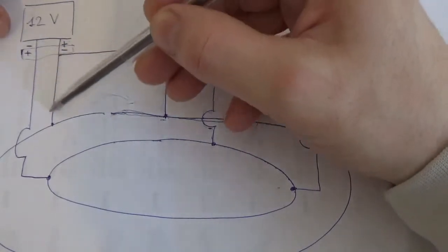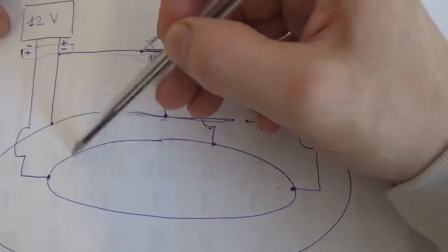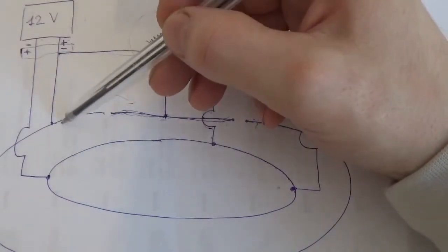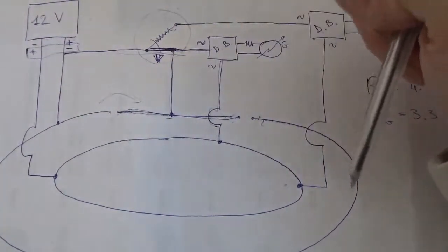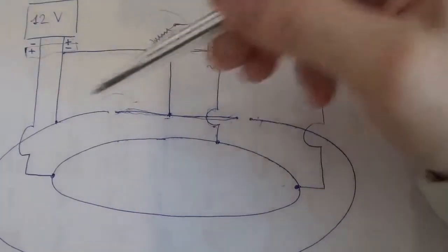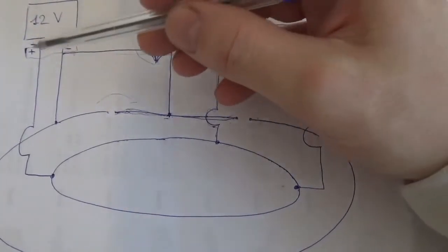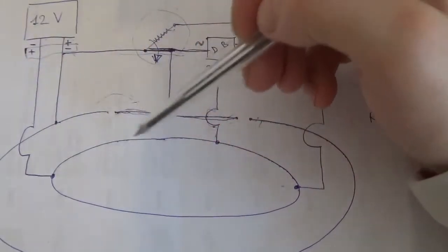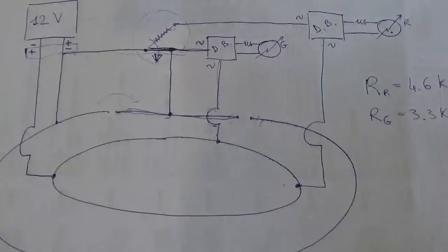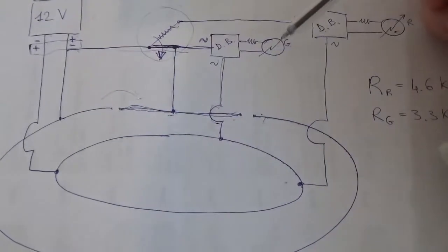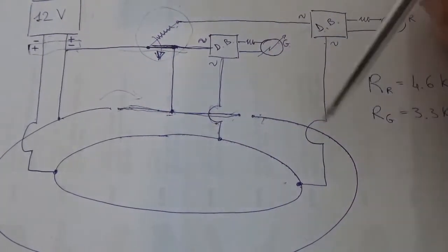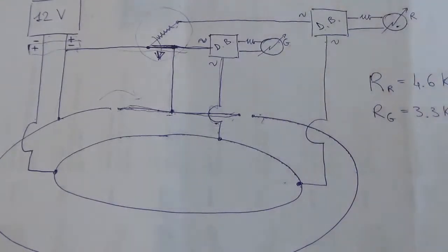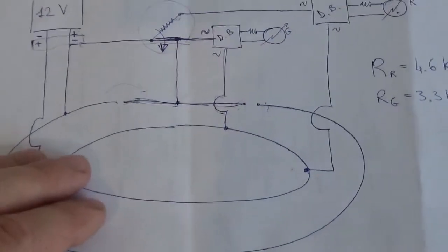In this other direction is going to power up this other side of the rail. So you can see that this outer section of the rail is powered up with minus, this inner one is powered up with plus, so there is a difference in potential and everything is working properly. There is power here, the light is on here, and everything here is off, as it is an open circuit. Now this is how the circuit behaves,